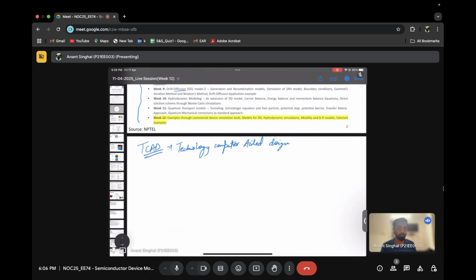Yeah, kind of. So what you can do in the simulation is directly change, let's say, the length of the channel of the MOSFET to various different geometries. So you'll get the idea, if the length gets shortened, which short channel effect is dominating. That is why these simulations help. And even after this, we have compact models to mimic this device design. As I told you, there are several compact models. Those equations are implemented in the SPICE simulators also to mimic the same IV.